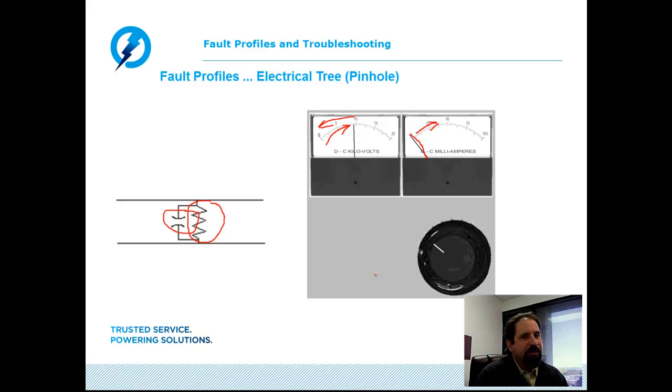Again, if you are using DC high pots, please be a little bit cautious, particularly with service-aged cables, particularly those of the polyethylene and cross-linked polyethylene classes, because these types of cables are very prone to treeing effects. Research and studies by EPRI and various members of the Insulated Conductors Committee have determined that DC testing on service-aged cables, particularly those prone to water treeing, could actually cause more problems or future problems.